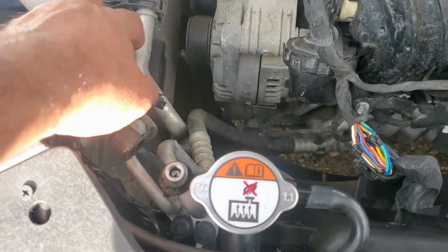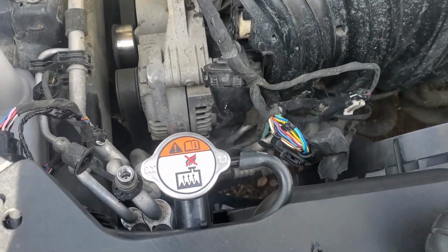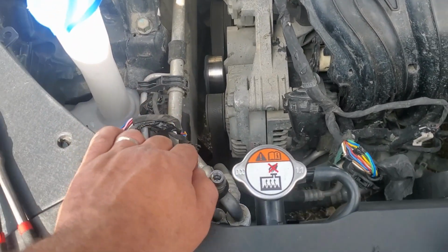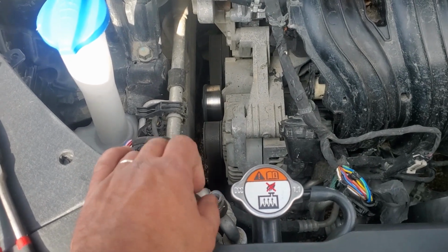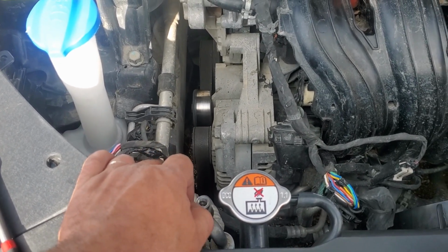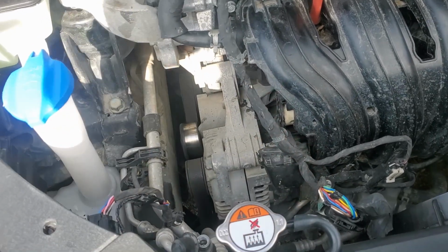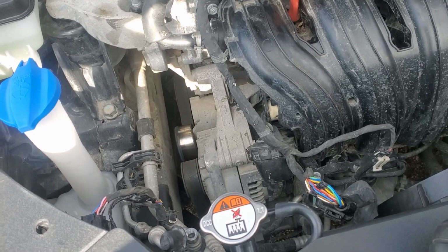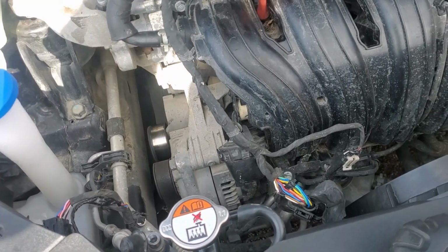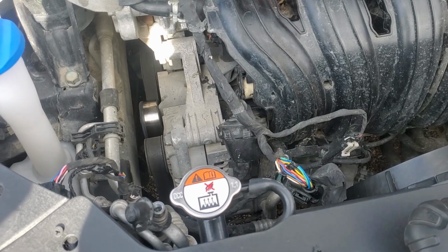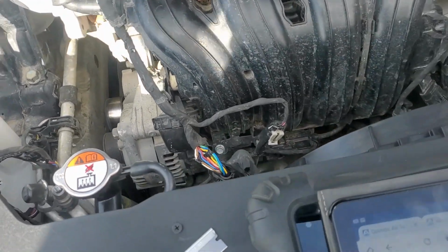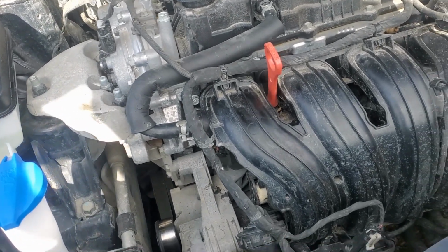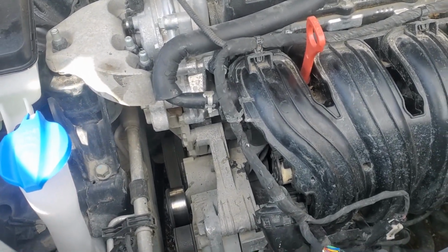With this one, when we unplug it, we have no voltage. So again, that signal wire could be shorted to 5 volts. It wasn't moving. Should we do the same thing, a disconnect test, and see what the values are?